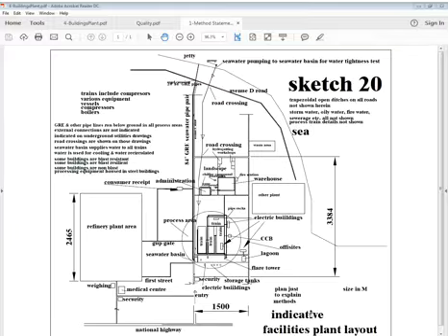Then various areas are there in the indicative plan, and it's written that trains include compressors, various equipment, vessels, boilers, GRE, and the pipelines run below ground. GRE means glass reinforced epoxy; these are epoxy-based pipes made with various processes we'll discuss somewhere else. Other pipelines run below ground in all process areas.